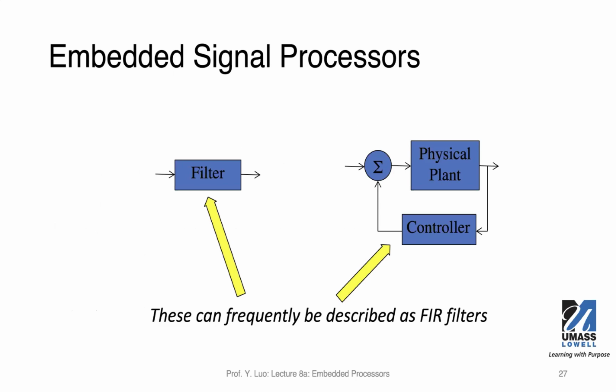Okay, so what we explained earlier was the filter design using digital processors, so that we don't have to have analog circuitry. We can use a microcontroller to perform the same operation. That will give us a lot more programmability. We can choose different sample coefficients.